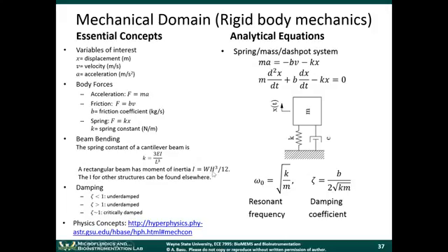So you can imagine what's going to happen if you have very thin beams, as is the case. When we microfabricate devices, we deposit thin layers of material, and then we pattern those layers. So the thicknesses of the beams will be very, very thin. That equates to small spring constants. So things become flexible, things that you would consider to be rigid, like silicon, which is a traditionally rigid material. But if you make a very thin beam out of silicon, that silicon will bend.